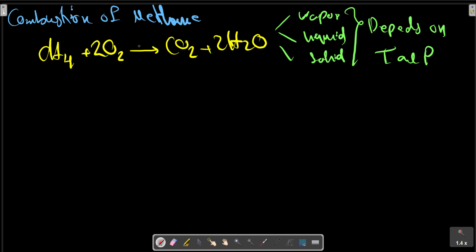In the combustion process, many intermediate products are formed during the chemical reaction. In this book, we are concerned with the initial and the final products and not with the intermediate products. But this aspect is very important in a detailed consideration of combustion. In most combustion processes, the oxygen is supplied as air rather than as pure oxygen. The composition of air on a molar basis is approximately 21% oxygen, 78% nitrogen, and 1% argon.